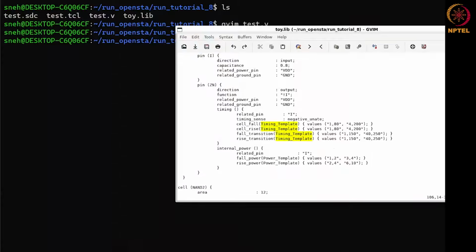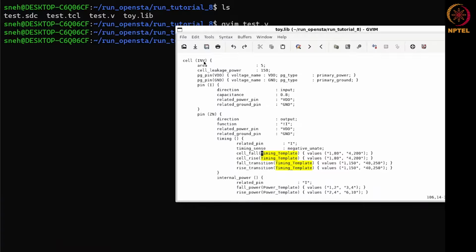We go to the cell INV, and corresponding to that we see the NLDM table for the delay. The other NLDM table is for the output slew, so we are not considering that in this experiment. The delay table is this one, and the values are 184, 200. This is a toy library and therefore the characterization points are only 2 for slew and 2 for load. In realistic designs there will be say 8 characterization points or more for slew and similarly for load.